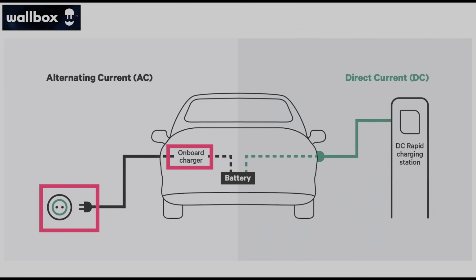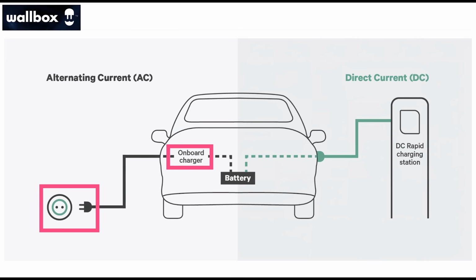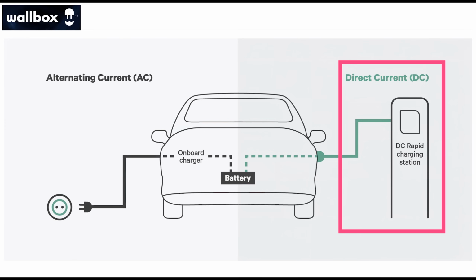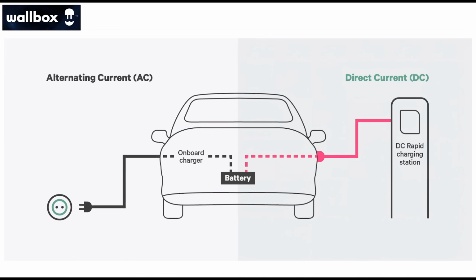Okay. The other thing I should say, and I'm sure you and everyone listening would know this, but there are two types of charger. There's onboard charger and offboard charger. So if you're charging your car at 7 kilowatts at home, that's actually using a power converter that's on the car. Whereas if you're charging it whilst driving across country, then the charger basically plugs directly into the DC bus, and the electronics for doing AC to DC is outside the car. Yeah, I think we all know that.